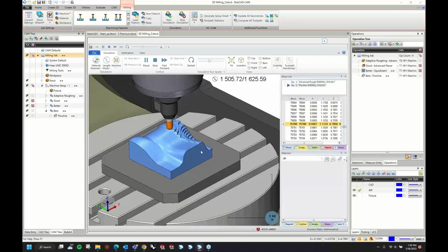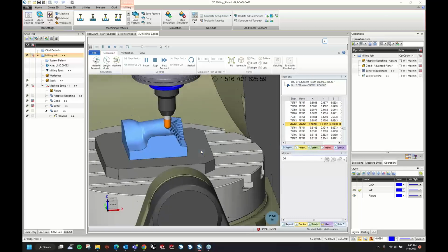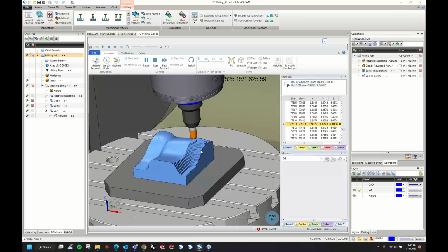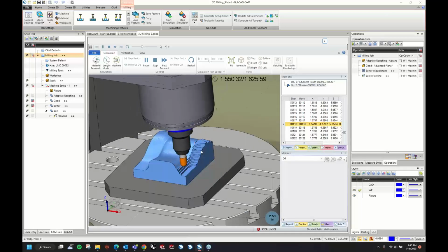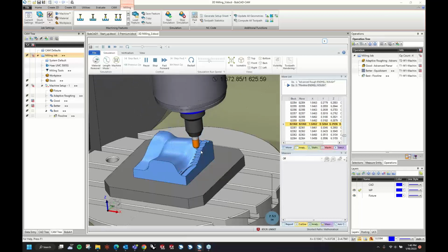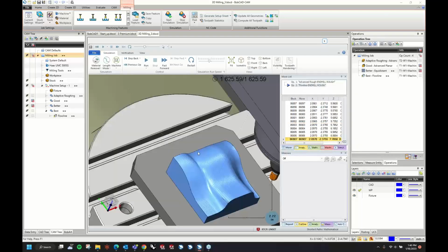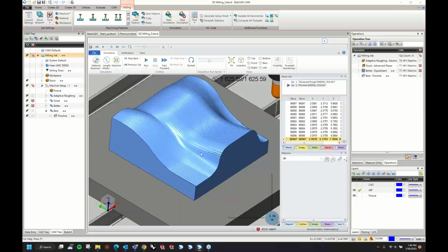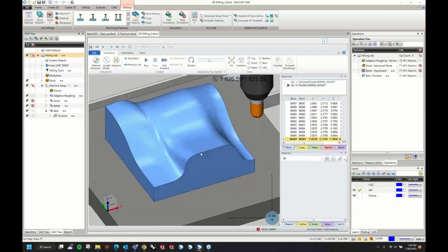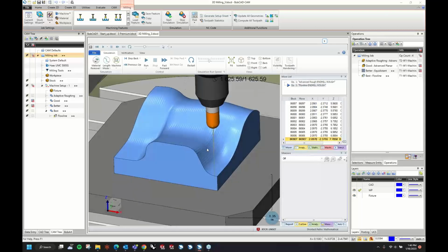The benefit of flow line is that it is a single surface selection. So you could just pick one surface and just hit compute and it'll cut it. Makes it fairly easy to use. So it did some linking there, and that's the thing that I don't really care for about that one, but it does give you a really good, consistent finish. You could always tighten that up a little bit to get a little better.